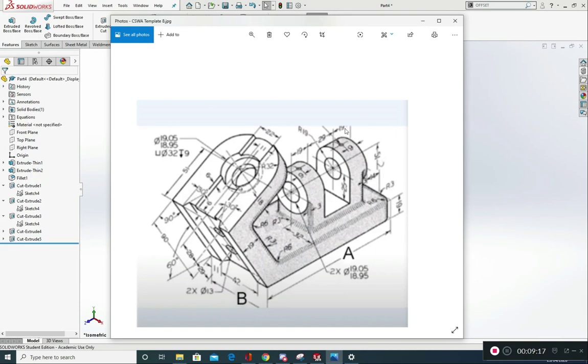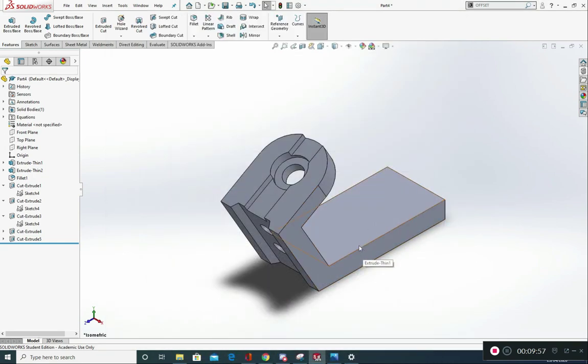I'm also going to use that 67 and divide it by 2 to get my centre point, which would be 33.5. However, I've not taken into consideration this gap here, which is 14 millimeters. So I need to do 19, 29 and 19 to give me my 67, divide it by 2 to get my centre, which would be 33.5, but then with that 33.5 I need to add this 14 to get the exact centre here where my plane is going to sit, which will be 47.5 millimeters. So let me just show you how that works on SolidWorks.